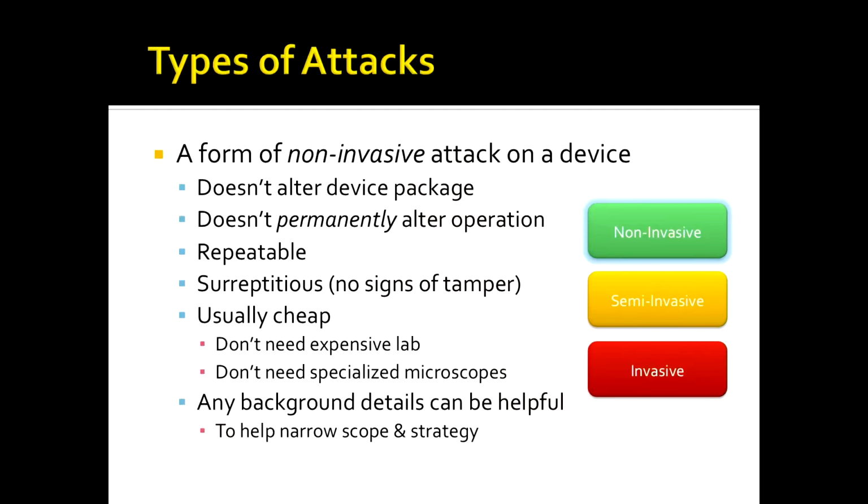It's also surreptitious, which means there's no milling or drilling or etching or things of that nature, so it shouldn't look like you actually did anything to the chip physically. It should just look normal. Another fairly important characteristic is that non-invasive attacks are usually cheap, so you don't need an expensive lab, and you usually don't need things like specialized microscopes or other expensive tools.